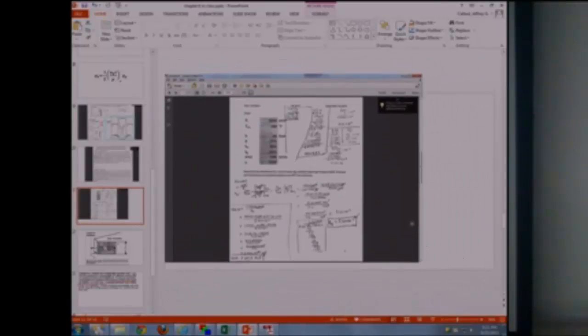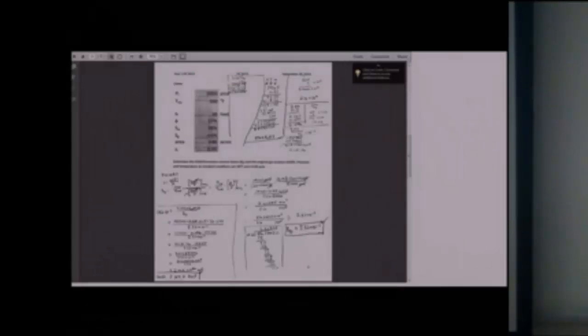So I think exhibited here is a good example of all the calculations you need in order to get the formation volume factor. Okay? So it's just the real gas law. I gave you Z. You didn't have to use the gas gravity, you didn't have to use a fluid properties correlation. If you had a computer, you would have just looked up B sub G based on pressure, temperature, and its impurities, and its gas gravity, or basically its concentration. But knowing a Z, you can calculate a formation volume factor.